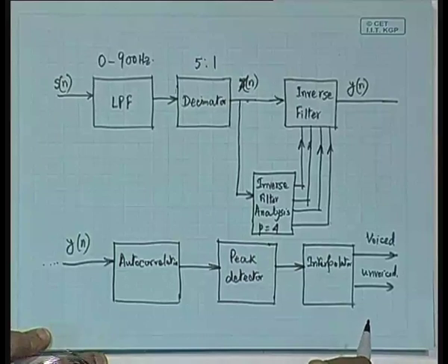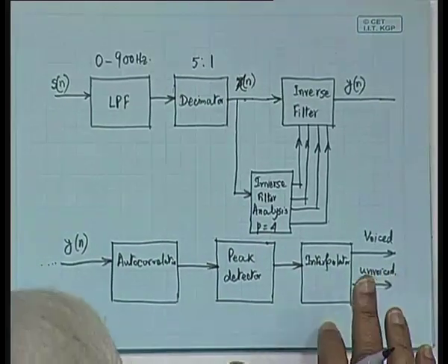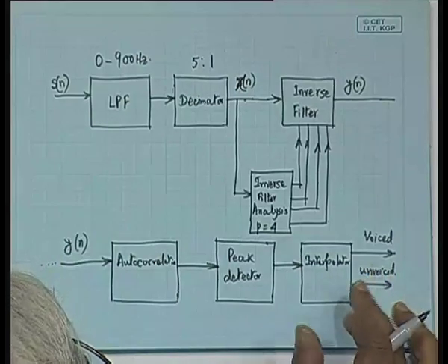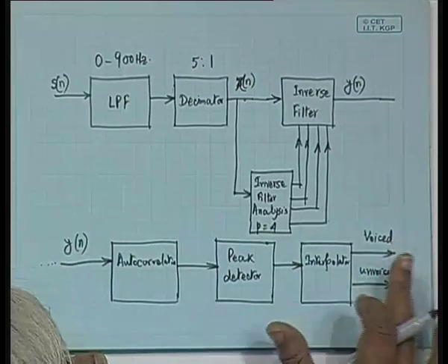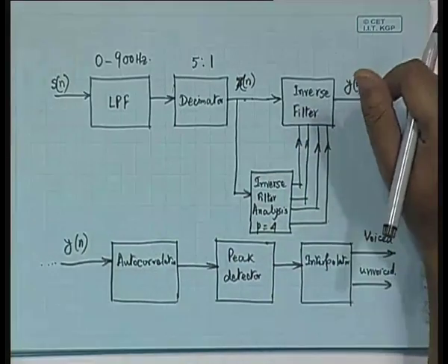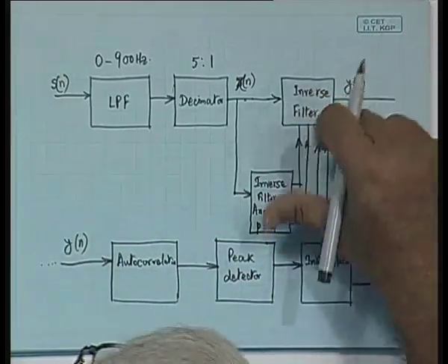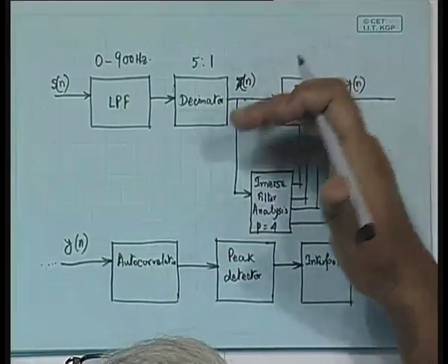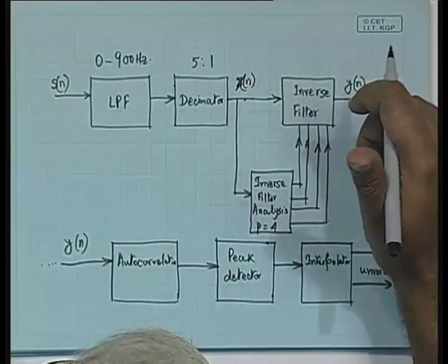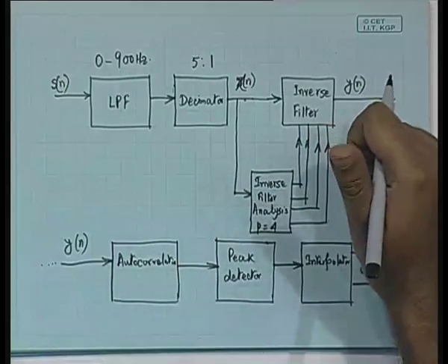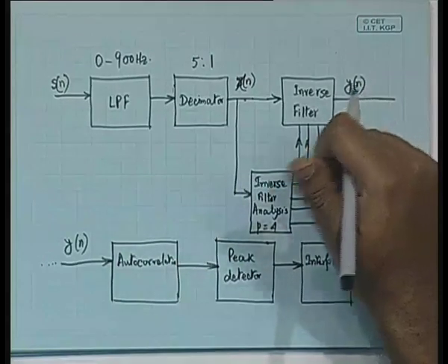Now this is really something very useful. Here we find a very good application of the LPC, that using the LPC parameters we are doing a kind of inverse filter and then have a better pitch period estimator as compared to the conventional approach we had studied.